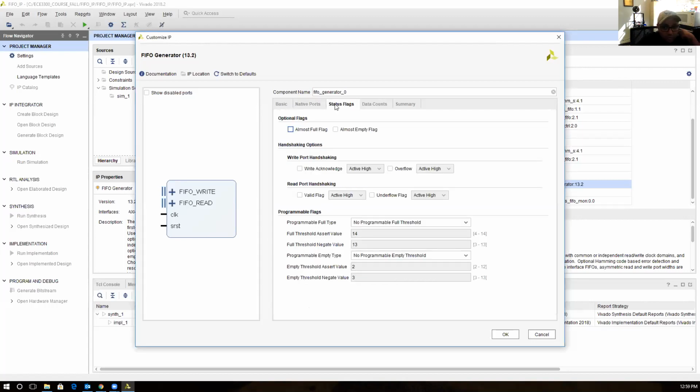Then the flags that we mentioned, right? So do you want full and empty? There is also something called almost full, almost empty, because it's working based on this FIFO counter, right? You can define that almost full can be high maybe if we reach 75% of the resources. Just like a warning for you. You understand what I'm saying? If you want, you can just say yes. Automatically in the manual, it says it is based on 75 to 25%. But I don't want it.